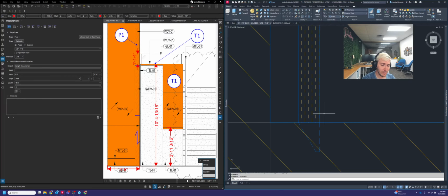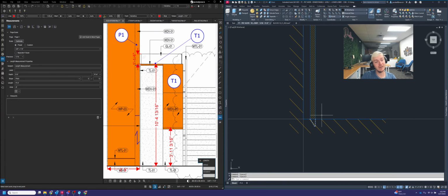There are cases where you won't need to scribe things like metal trim. Metal trim typically won't get scribed because it's harder to actually scribe that, being that it's metal. You have to have a special saw blade to do that. It's also hard because whenever you have a metal finish, if you cut that, usually it cuts into the actual metal itself, which shows a shiny edge, which we'll talk about more. But just a heads up, when you have scribe at the floor, typically you won't see it on metal, but you'll see it on laminate, veneer, different things like that. So you're going to see that quite a bit, or solid too.